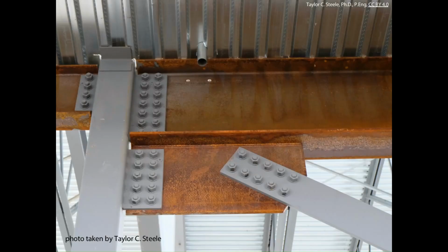They're all bolted together using different bolts. We've got a flat plate that got custom shaped or cut out using a laser to make this gusset plate connection. And then we've got a flat bar brace coming in to connect to that gusset plate. Okay. Oftentimes we bolt things together, but we can also weld them together. Here's a smaller structural bolt.